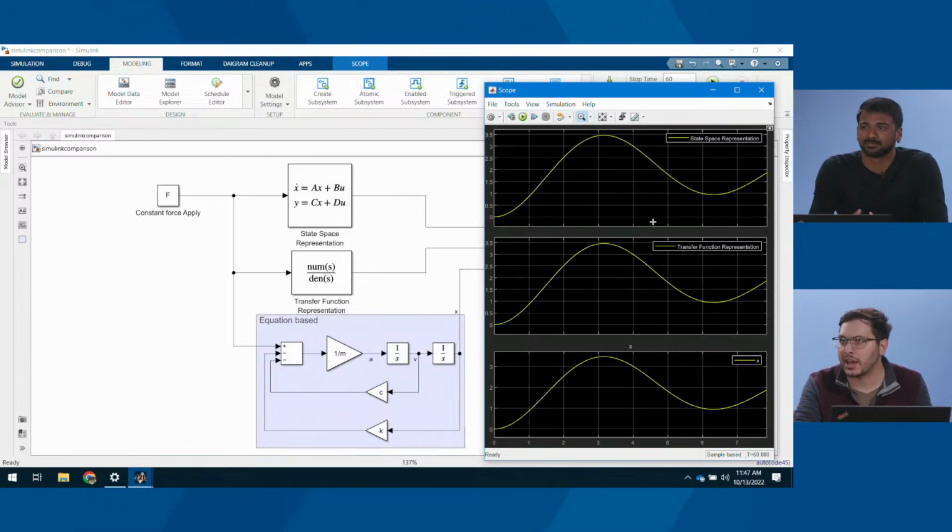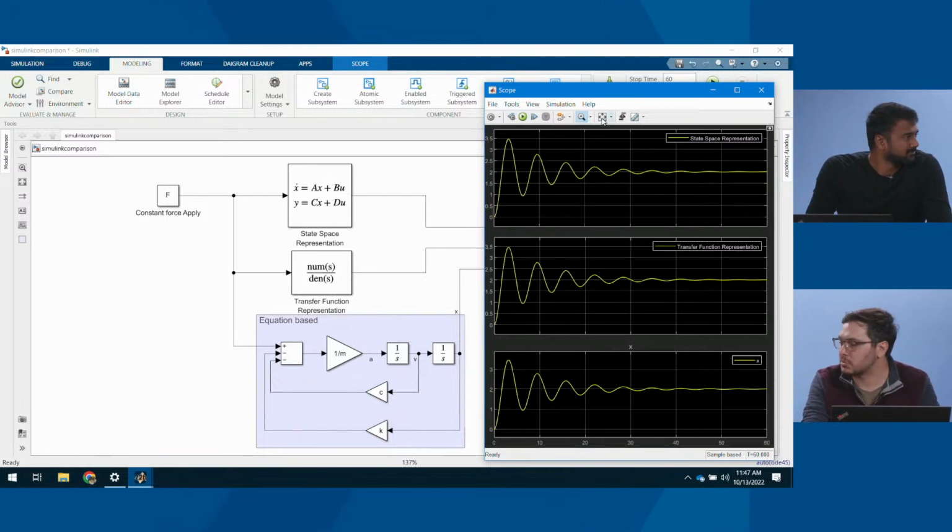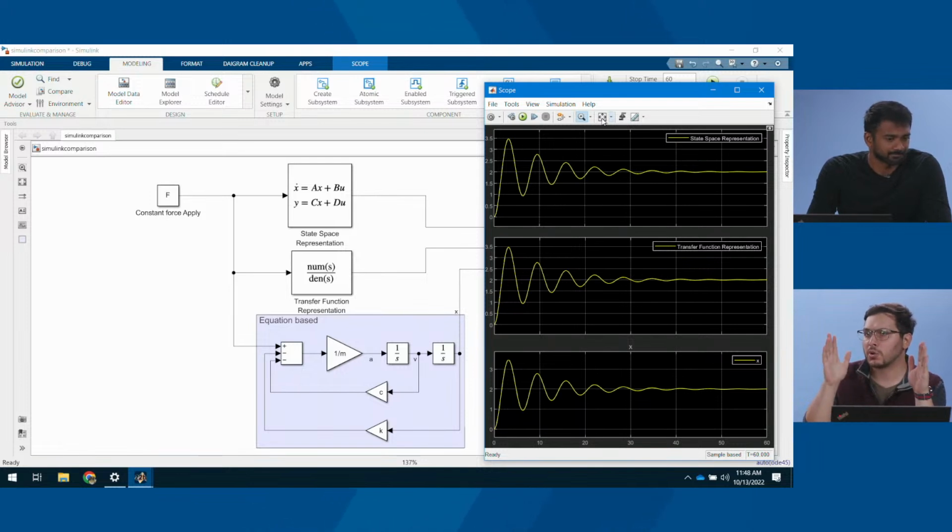It's going to depend on your system, what you're modeling, and how detailed you're modeling it, to determine what an appropriate step size is. If I added some nonlinearities to my model, the solver will try to handle those. For really intense things where a lot is happening in your model, it will shrink down the step size during those transitions. Then when it's at steady state, it'll go back to taking really big step sizes. So variable steps are really useful for plant modeling and continuous systems, where you've got a representation of something physical that's happening.